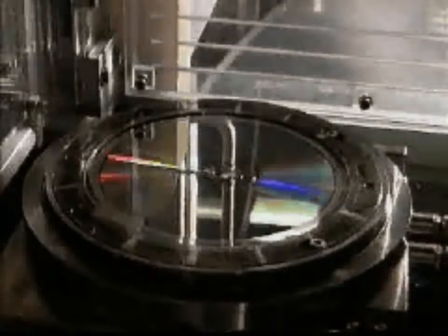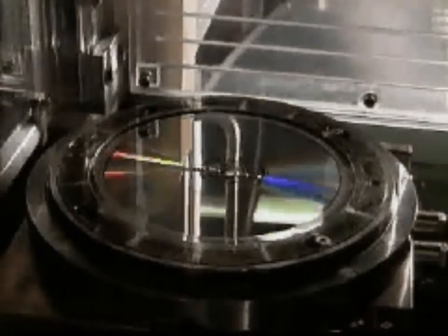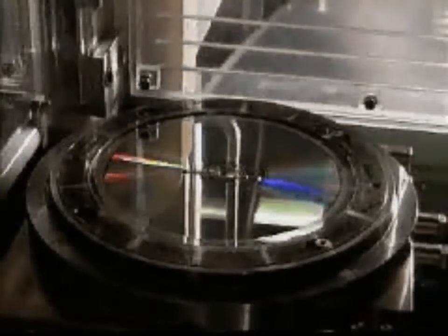After the glass master has been recorded, it's passed into a second clean area where a nickel stamper is grown onto the glass plate. That nickel stamper is peeled off the glass plate and can be used to replicate the discs. The stamper is then fitted into the bottom half of the mould, which forms a cavity with the top half. Into this cavity, liquid plastic is injected, which freezes off in about 5 seconds. A robot arm then takes the disc out of the cavity and passes it to the next stage in the process.